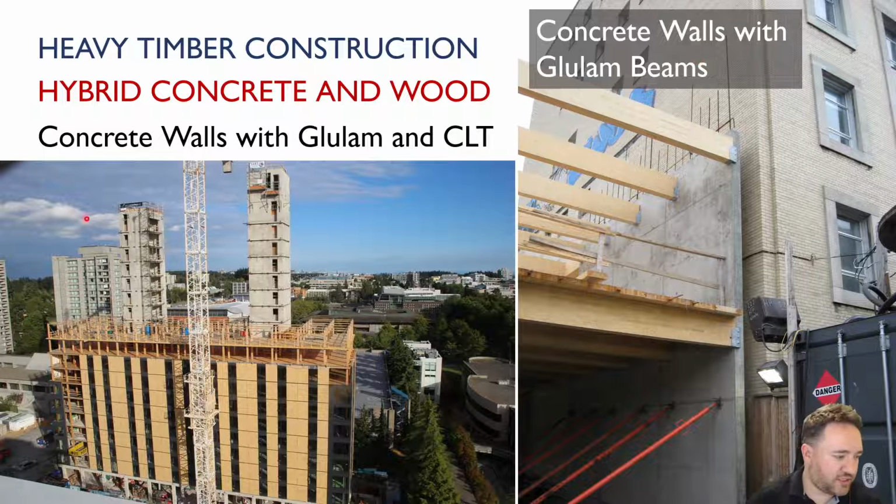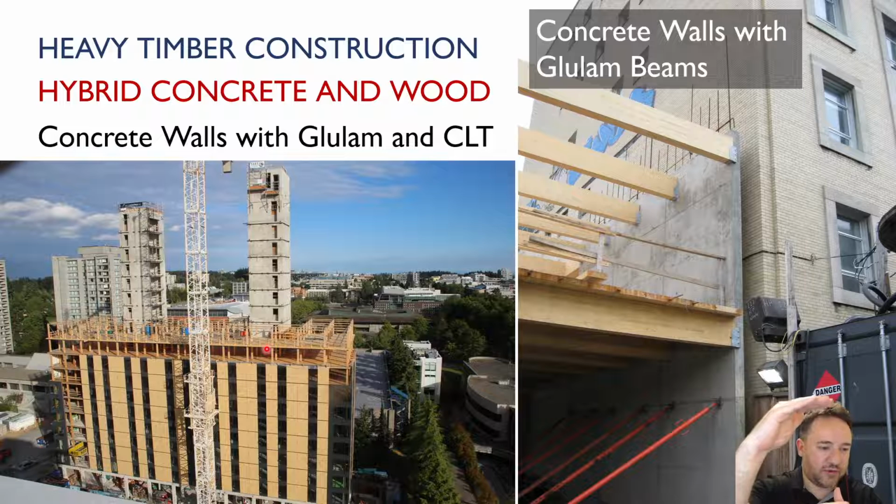Another thing that you'll notice here is the first story is made of concrete. It's a concrete frame. The reason for that being, at that first story, they can space the columns further apart. So if they have assembly spaces or retail on the first floor, they make that out of concrete, and then the rest, where they can afford to have these really closely spaced columns, they made out of timber. And that's a very common thing to do as well, to make a first story podium, like a commercial area, out of steel or concrete, and then make the rest of the building out of timber. On the right is another example of a concrete wall just connected with some glulam beams, which looks very nice.